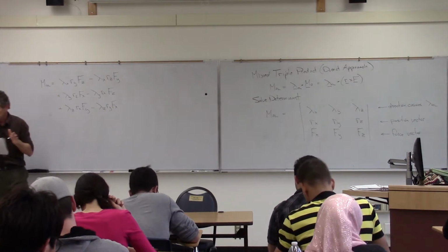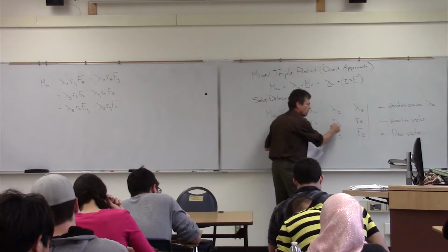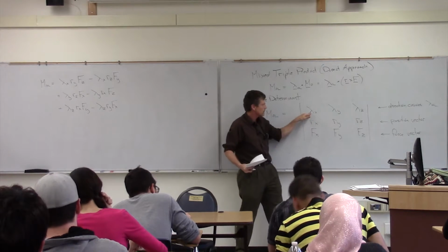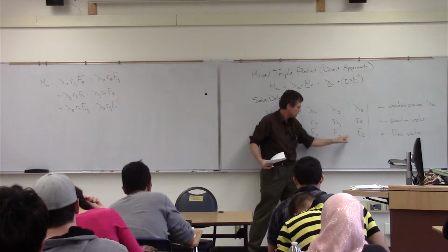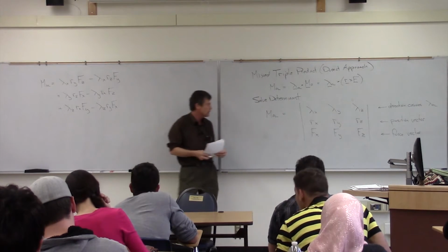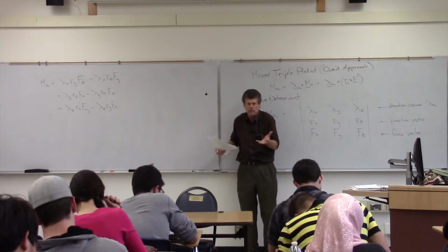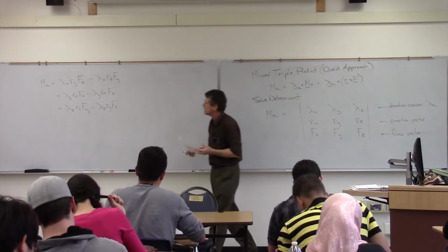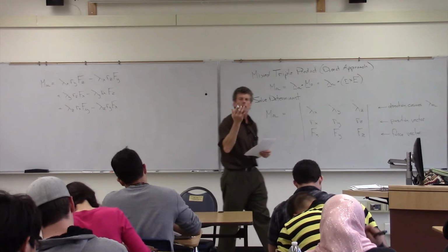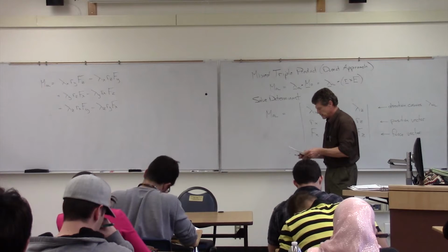OK, so that's basically it spelled out. But again, it's just solving this determinant, Rx, Ry, Fz. And then we go the opposite direction there, Rz, Fy, minus, because it's going the opposite sense. Those are the two terms there. Then we move over to the y. If you want to solve it via the minors, you can do it that way. But basically, it's the same thing that we did with the cross product. But now what we're doing is solving for the moment along a line. And again, it's all done in one step, which is very nice.